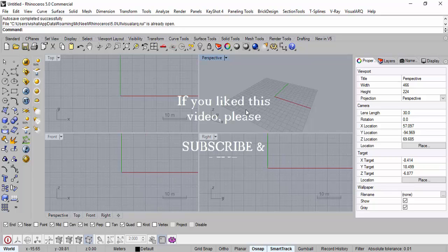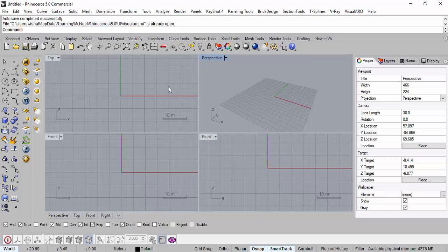When you do a large model, right, you can afford for things not to join exactly precisely. A gap of 1 centimeter or 1 mm, 2 mm is fine. It won't make a difference even when you build it. But if you're doing something like a design of a mobile, let's say, it matters. The accuracy has to be 0.001 mm, right? Every millimeter counts there. So you need to decide what accuracy you want. So when we say large meters, that means the accuracy is large. We are doing something very large, so the accuracy reduces. You getting it? Okay.